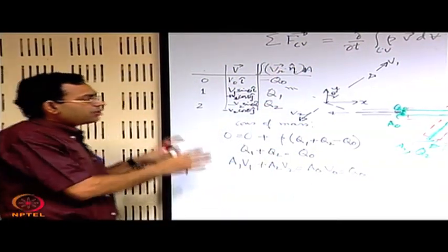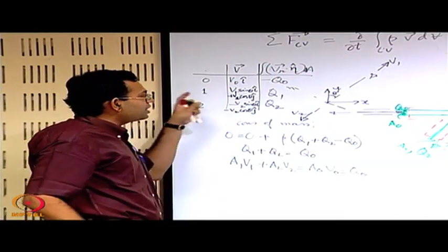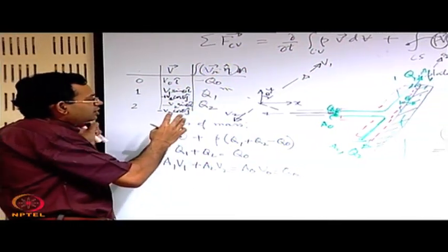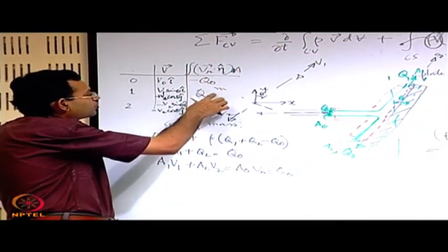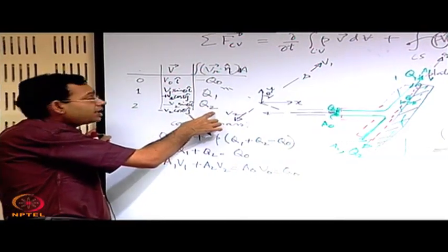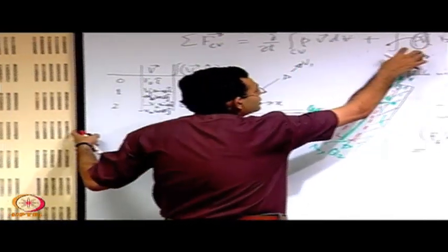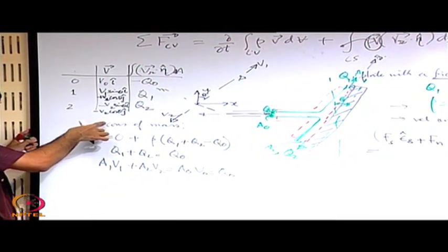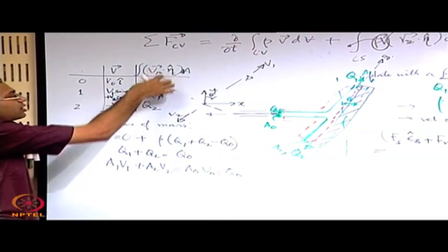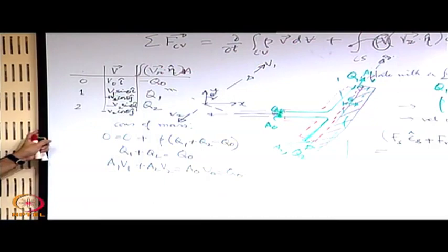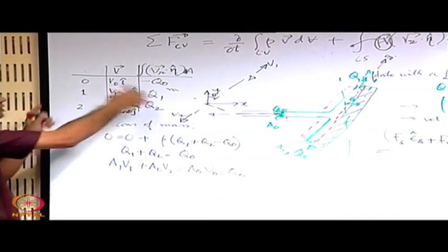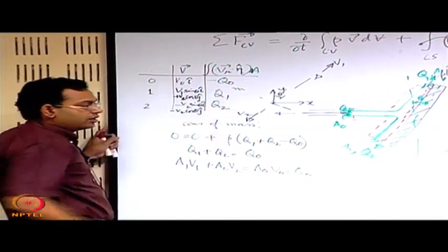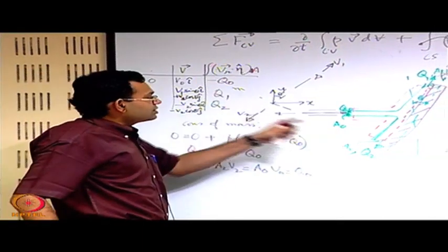See, this is very straightforward, but I want to emphasize it because this is a place where students make mistakes many times. By default, it is common to think that the outflow boundary gives rise to a positive flow rate, but the velocity that comes with it has nothing to do with the flow rate. So, you have to write that in proper vector sense. This plus or minus term has no conflict with the flow rate term, and you should keep that in mind. Otherwise, just by inertia of writing, you might write this in a similar sense as you have written this. Okay. So, let us now substitute that.